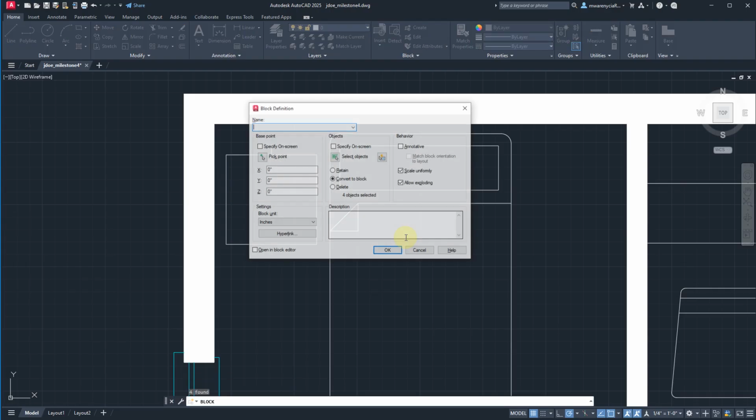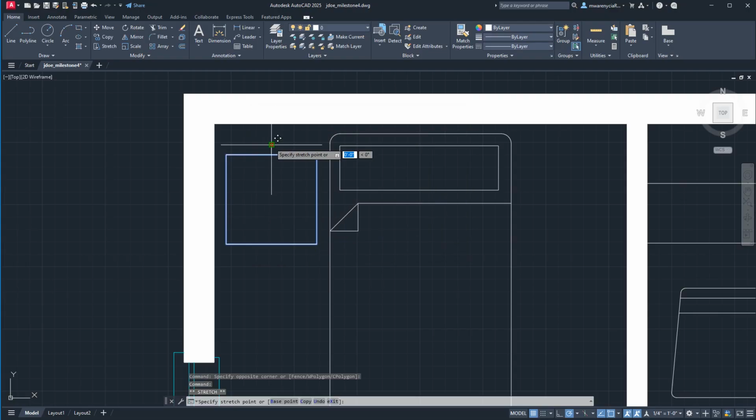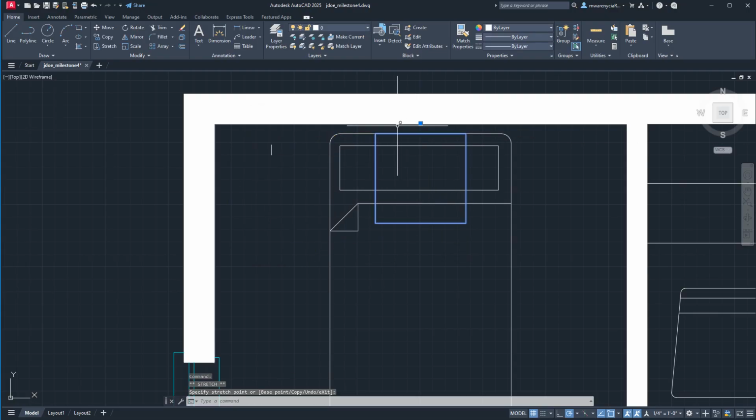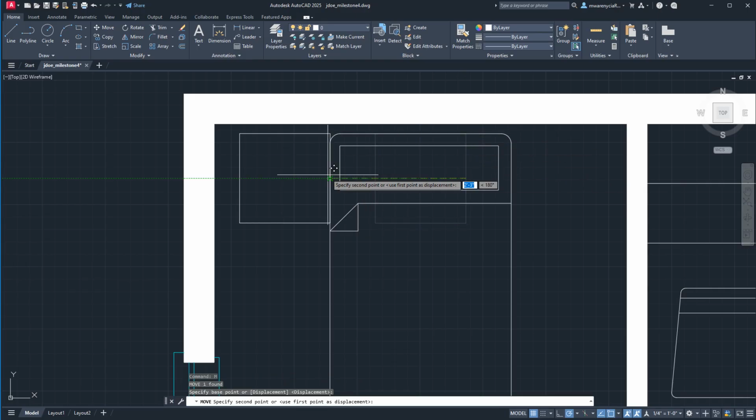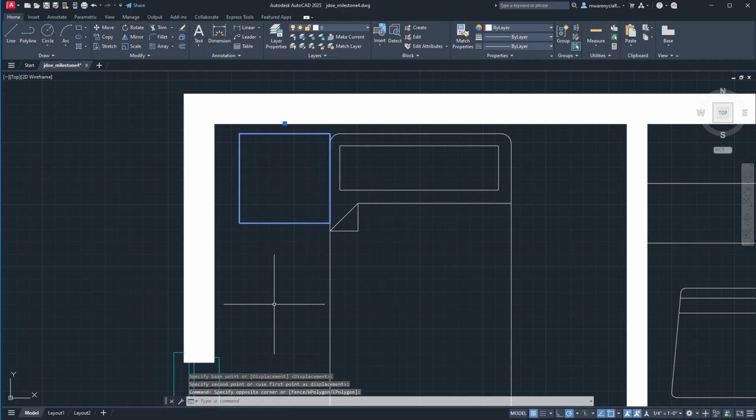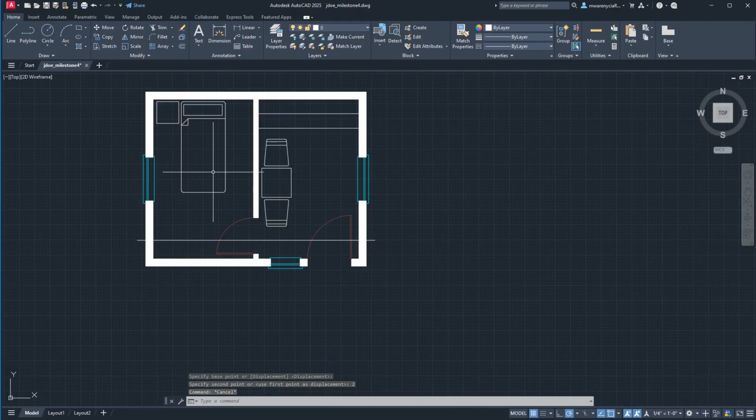We'll block this furniture nightstand 18 square. Picking a point, we'll go right there, hit OK. I'll move it right here to associate this. And then we're going to grab this face right here, snap it to that, and then we'll move it another 2 inches so that it's nicely aligned right in that corner like that.